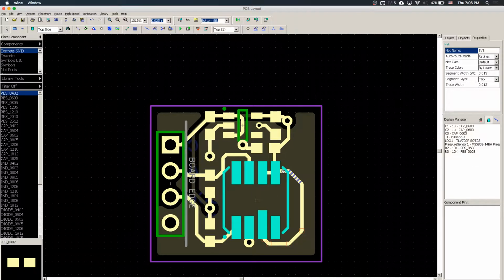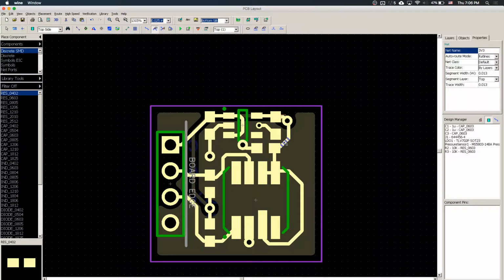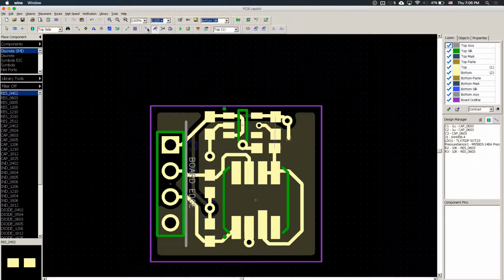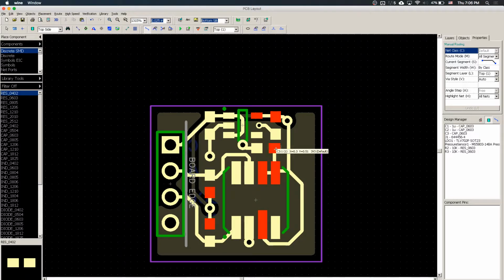And if the bypass capacitor is used to reduce noise of one pin, you want to make sure that the signal coming through is passing through the capacitor before getting to the pin. So for example, the VCC is coming from here, goes to the capacitor pad and then goes to the pin. What you can also do is connect it directly here, and the capacitor will be outside the pin, and this is less recommended.